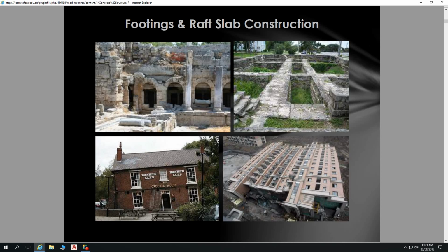Down at Seacliff, not far from the Seacliff Hotel, they just fixed up the balconies with the cantilever concrete. It was just ready to fall down. You see all the reinforcing rusting away. It was incredible. It diminishes the thickness of your concrete because it's busting concrete off the bottom. Then you no longer have the bond between your concrete and your steel reinforcing, so those two aren't working in concert. Eventually your steel rusts away completely, not having any tensile strength whatsoever.